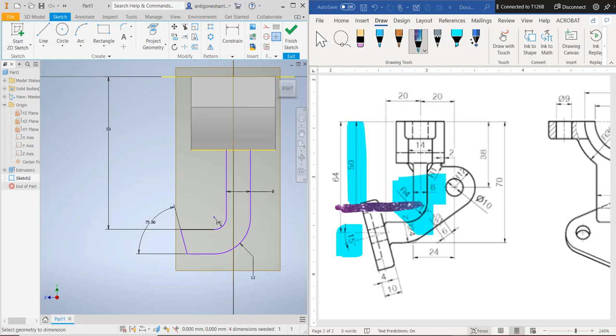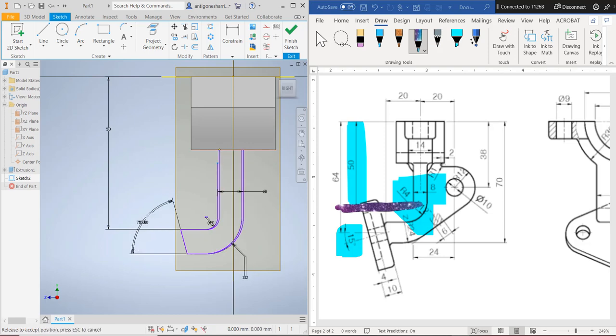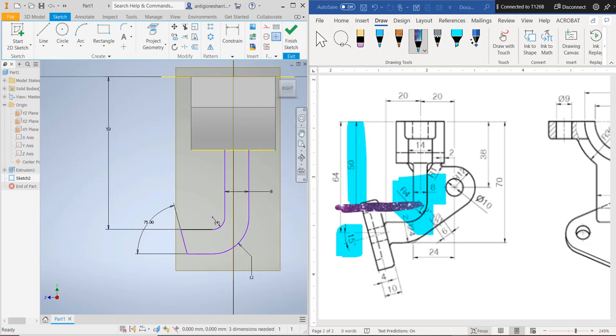Now you notice it's still not fully defined. You notice that? Most of it's blue. That's the reason it's not fully defined, because I can wiggle it. Remember that? I told you that. How do you find out if it's fully defined? You wiggle it. See what happens. This line is not properly touching that one. Now it is. Is this one? Yeah, it is. That one's locked. See, when you wiggle it, you find out what's missing. So its position is missing. Its position on the drawing is given in relationship to, I didn't mean to cover the numbers, just circle them. Its position is in relationship to what?